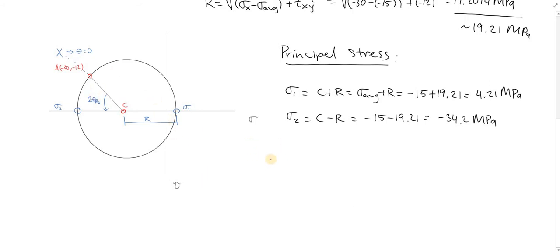So that angle there, we can simply just find this from the geometry, right? So if we look at the height, let's use a different color so it's easy to find. We'll look at the height. So from this until it cuts the axis, this is just the same as my shear stress, which is my -12.